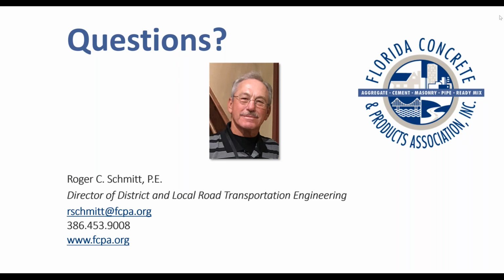Let me talk about something else too. Now they're doing the full depth reclamation, where they take the existing asphalt and whatever base is underneath it, and they pulverize it all, and they are using cement in that process.